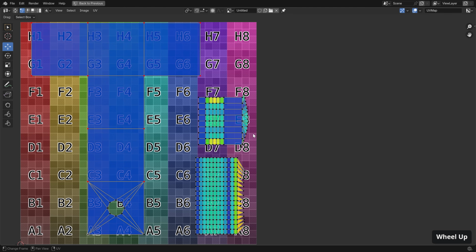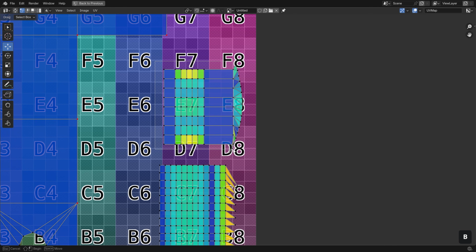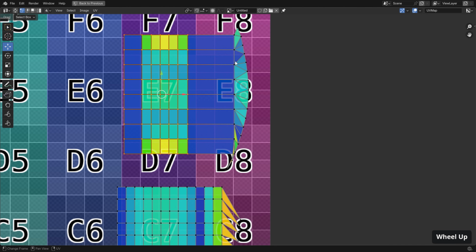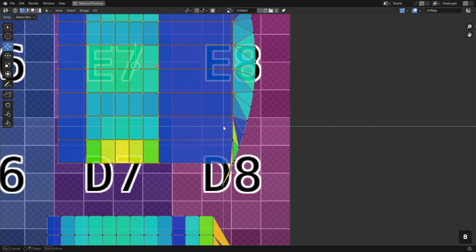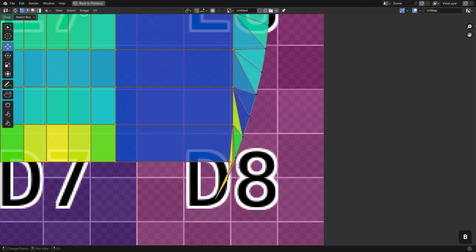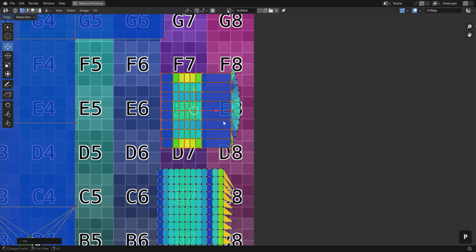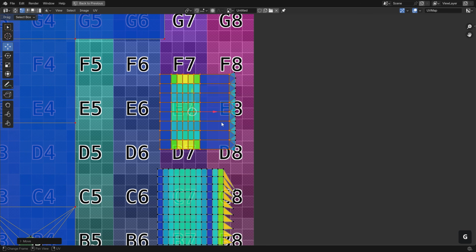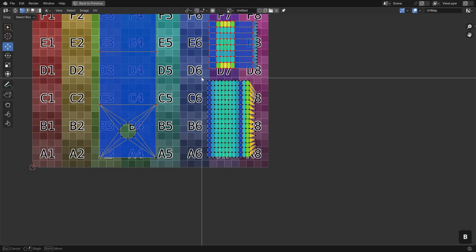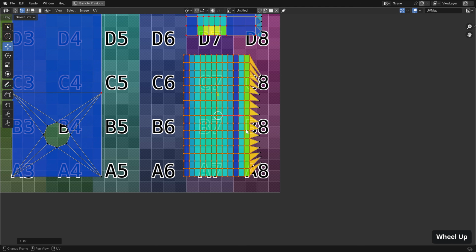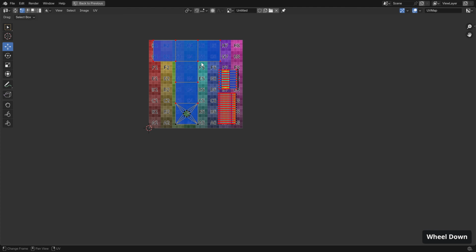Now we're going to do the exact same thing for these other sections here. We're going to select what we want to keep. So let's select these vertices here. Let's make sure we only select the correct vertices. Let's then pin these. And now if we move this, it will update the UVs here. So it's pretty straightforward and we get a nice clean result. Now lastly, the spherical part here, let's pin these as well, move these, and voila, we're done with our UVs.